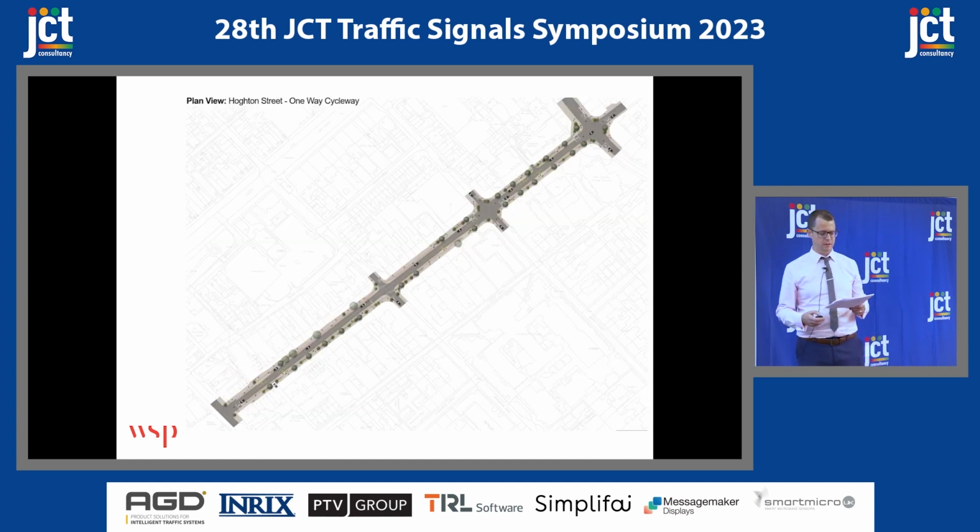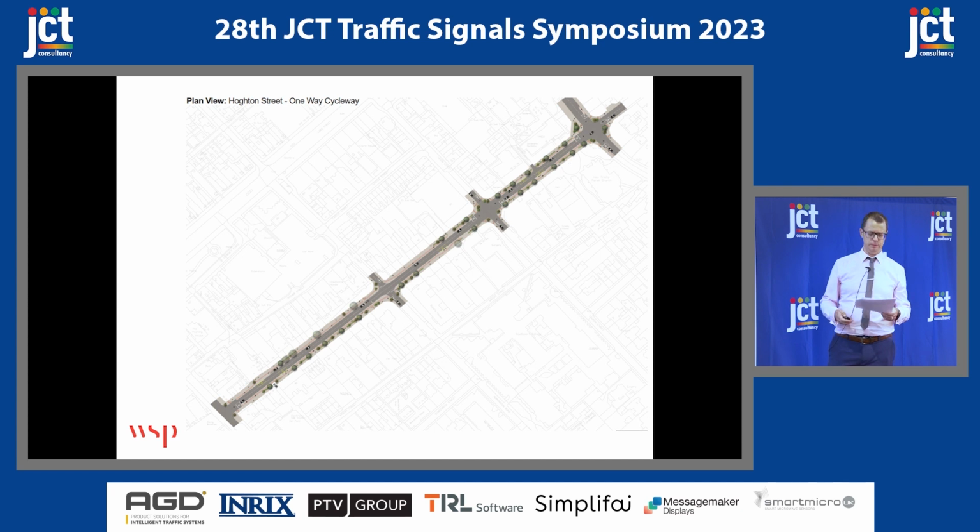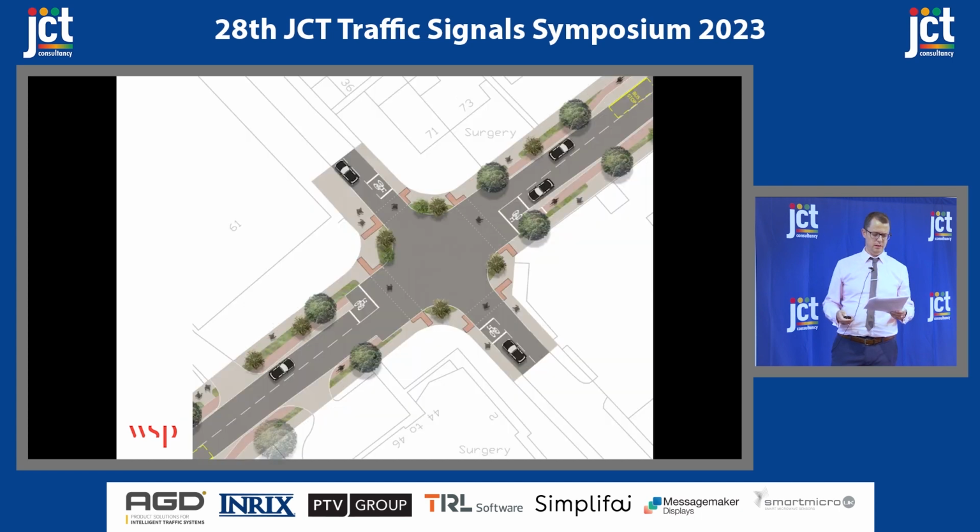So I did. This is a concept design for a road in Southport put together by my transport planning and landscaping colleagues, which makes use of the layout. The concept design provides segregated with-traffic cycle lanes eastbound and westbound along the corridor, with both directions using the alternative cycle gate layout. This is one of a number of different junctions along the route.